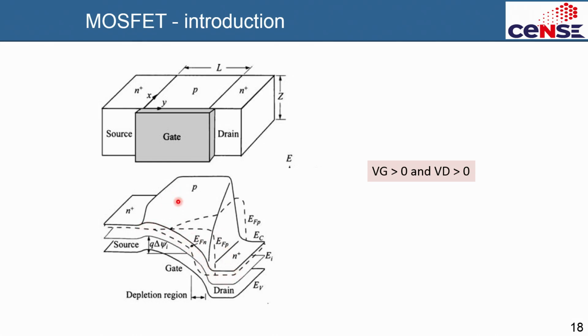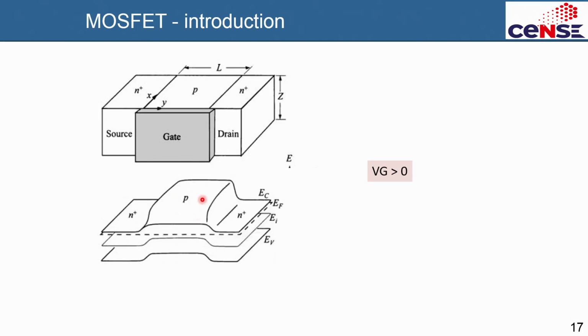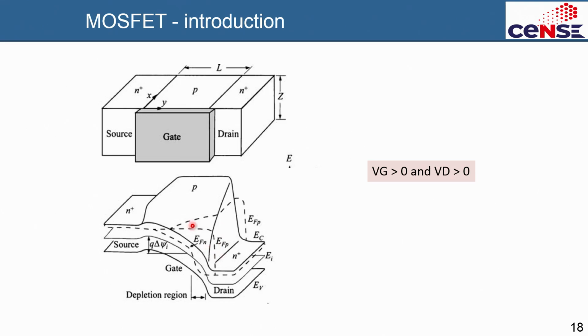The moment you turn off the channel, it will go back to something, you know, this is not a channel turning off, this is the drain voltage being 0. But even if you turn off the channel, the inversion will vanish here. Even if this voltage difference exists, you will not be able to get a current. So this is the condition when the gate voltage is also moving towards threshold, and the drain voltage is a good amount higher, so that you have a band diagram like this.